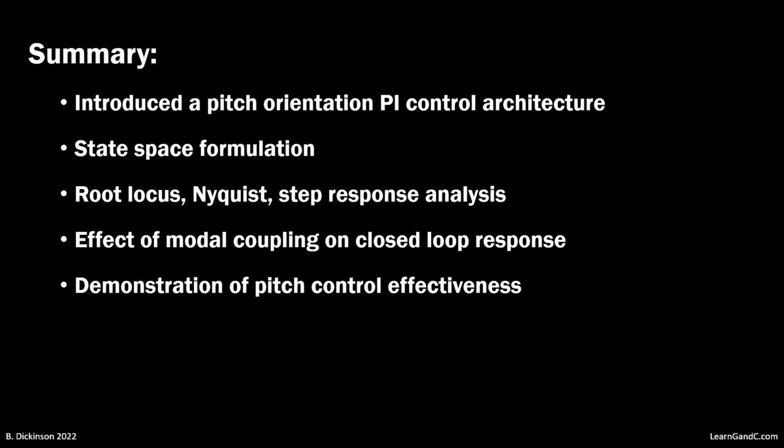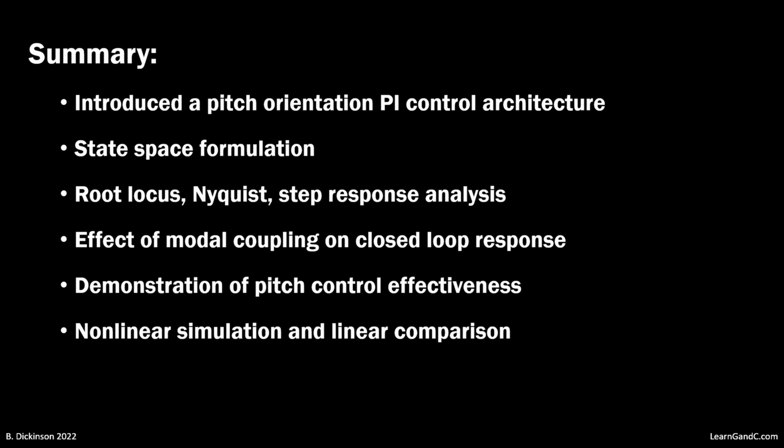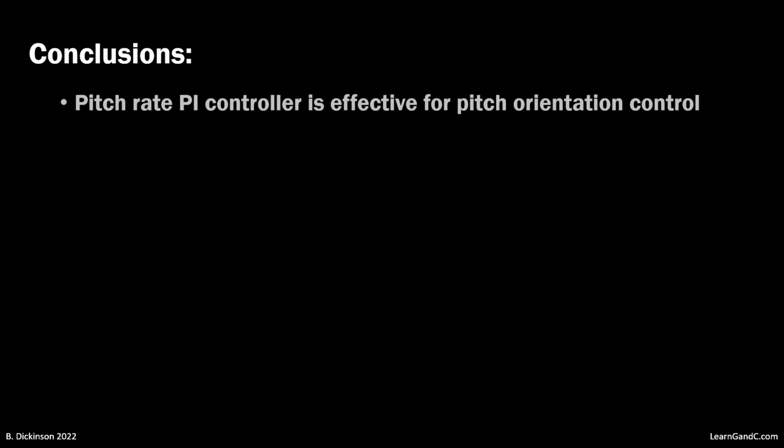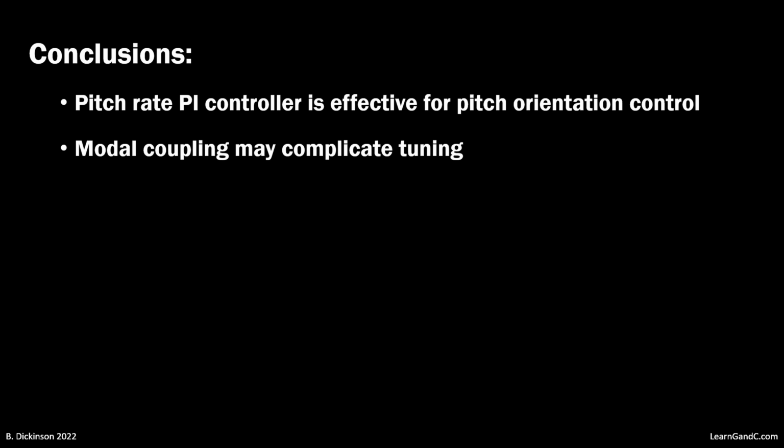Moving on to the nonlinear simulation, we showed the effectiveness of the pitch rate tracking controller. We also compared our results to the linear simulation. And finally, we sought to improve controller performance with faster actuation and briefly re-examined the achievable performance. From this lesson, we've learned that the pitch rate tracking controller is effective for pitch orientation control in the sense of providing a responsive and well-behaved change in the pitch angle due to push and pull of the control column.